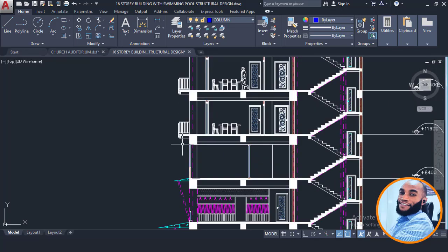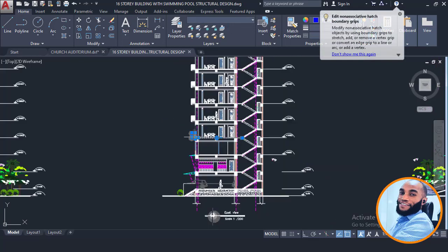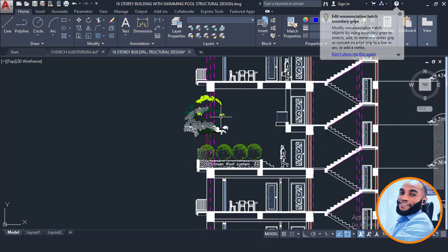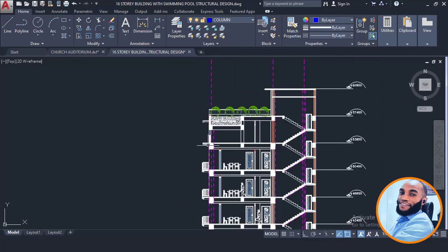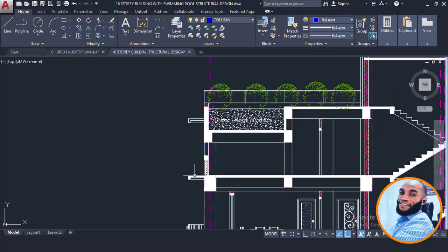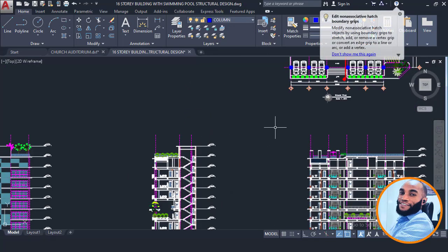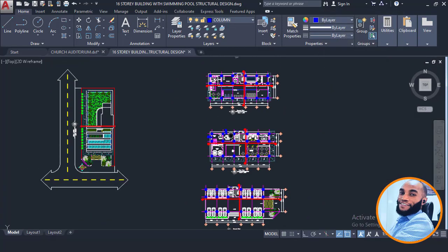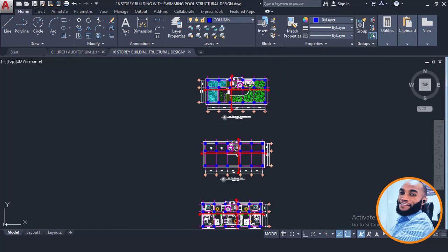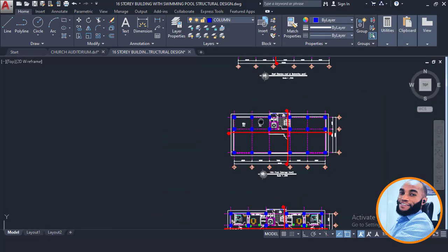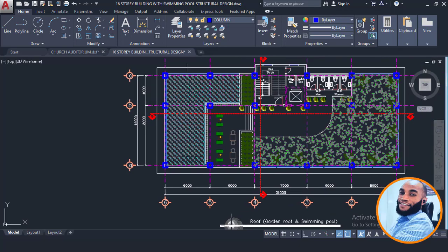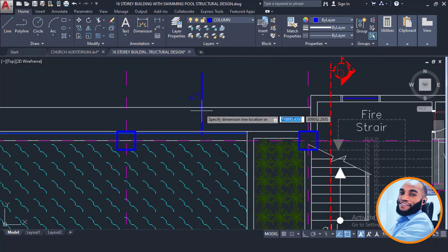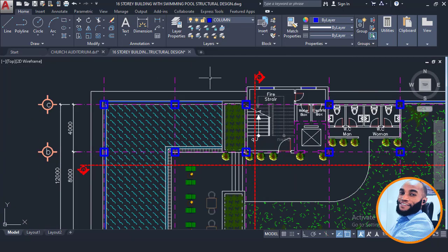So there's a cantilever basically from the 2nd floor all the way down to this other place here, and it jumps this floor and continues all the way down to this place here. Okay, so that lets me know that there's a cantilever at this place, and it is typical all the way up to the 15th floor. Yes, and also to the roof, because the roof also has it, which is basically the roof perimeter, I think. Yes, it has it too. So basically a cantilever lies all the way up to the roof.